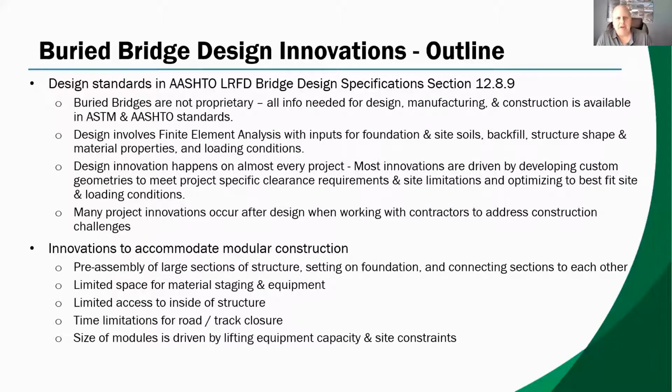So what am I talking about with modular construction? Well, for these structures, they're usually larger span structures. It involves pre-assembly of large sections of the structure, transporting it or lifting it onto the foundation, and then connecting those modules to each other after it's in place.